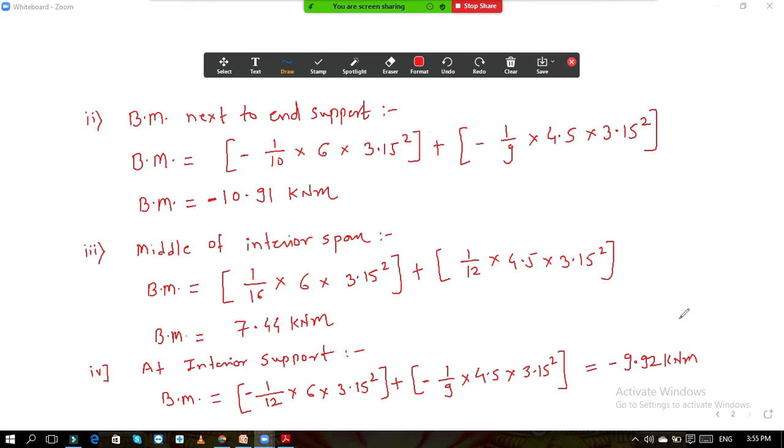So all these are the bending moments. Okay. So from all these values, we will choose the maximum value. In this, don't look at the sign plus minus. We want the maximum magnitude to check the depth. Why we are not looking at the sign? Because the sign is there for the sagging moment and hogging moment. If the bending moment is sagging at that point, then the coefficients are positive and therefore the sign is positive. And where the bending moment is hogging moment, at that point the coefficients are negative, and that is why the bending moment is negative. So we will look up for the maximum magnitude over here.